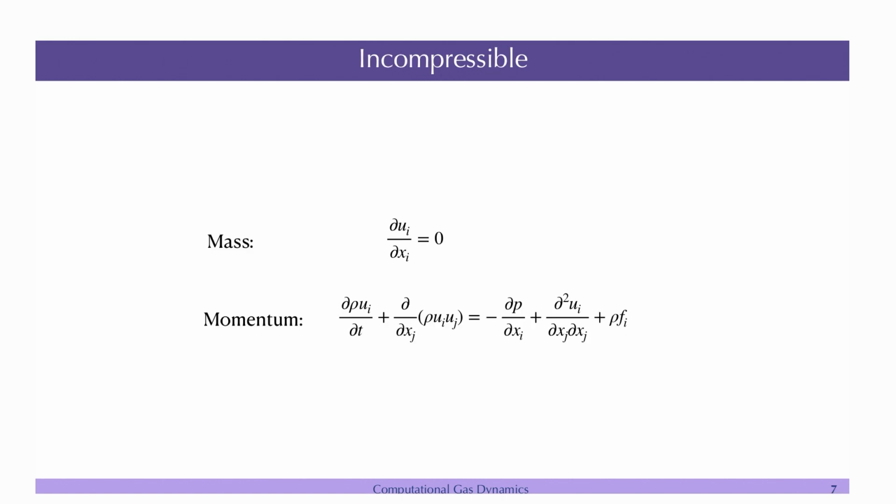Okay. And this is the approximation in the incompressible. Remember, no fluid is incompressible in nature, every fluid has got compressibility. Okay. But as we discussed earlier, for example, air is more compressible than water, right. So, in certain regimes, the compressibility does not matter and the fluid behaves almost like an incompressible flow. So, this assumption basically makes the physics much simpler.